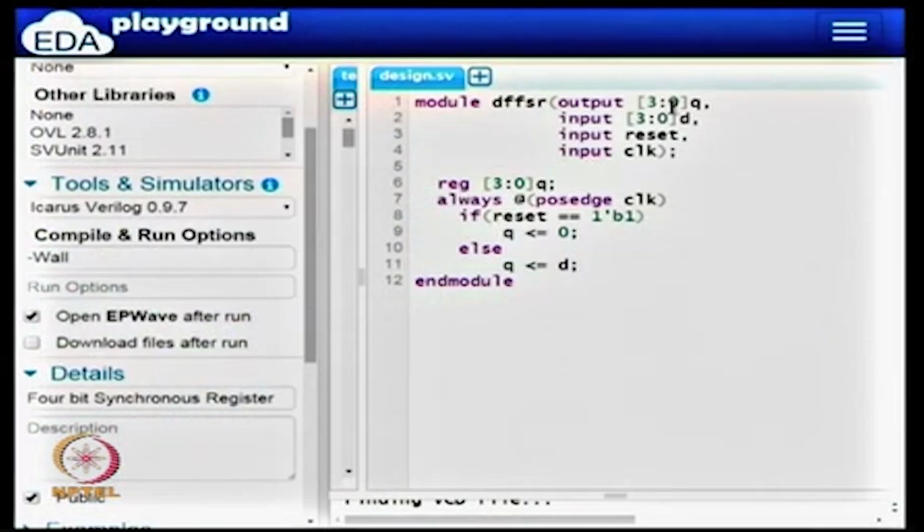So it is not correct to go back and ask, what is this software feature that I have? I have this software feature in C and C++, how to do that in Verilog? That is the wrong way to approach hardware design. The way to look at it is, in hardware I want this, how do I model this in Verilog? So Verilog should not be thought about as a substitute for a sequential language like C or C++.